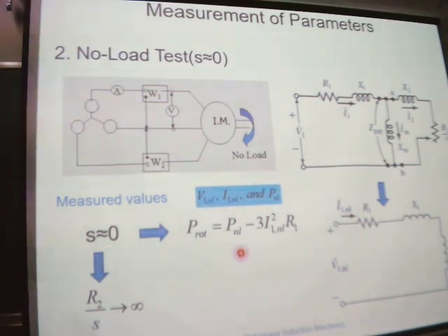Just the difference of these two powers gives us the rotational losses. So using this experiment, we can get the rotational losses.